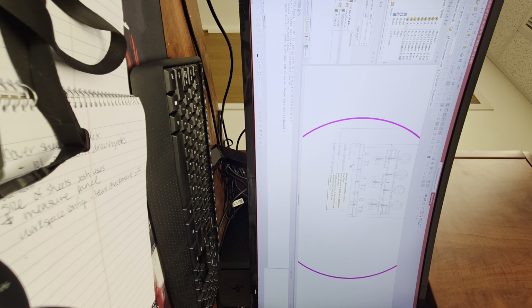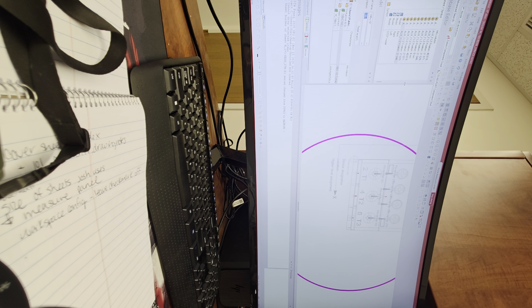Also, your starter, for example, could be one of those contact points, as in, technically speaking, you could add this auxiliary contact that we were just looking at into T2 and T3, meaning all of these individual points are possible insertion points for something else electrical, like another expansion of something else. Yeah. So how do these two pieces now mount together? In the database editor on your left side, where all your little yellow spots are, expand the name, or make this window twice as big just temporarily so we can see it all.